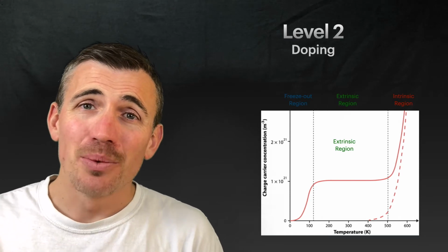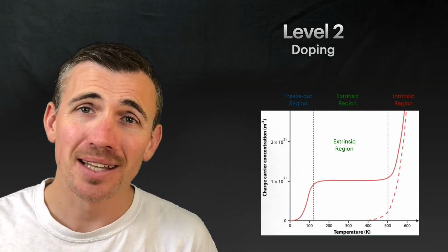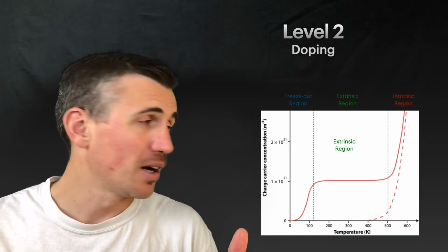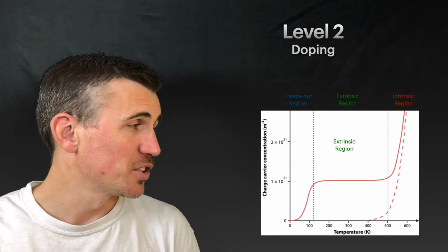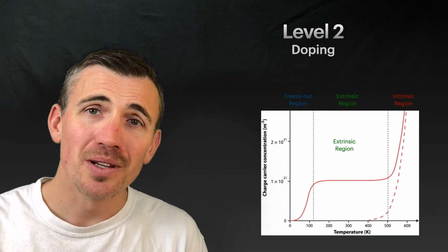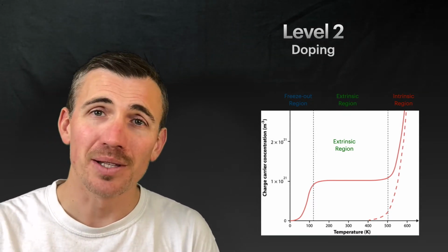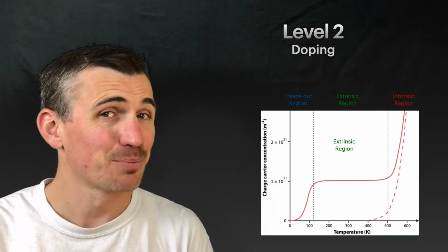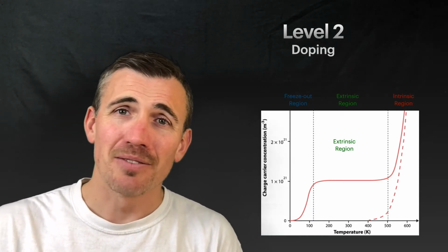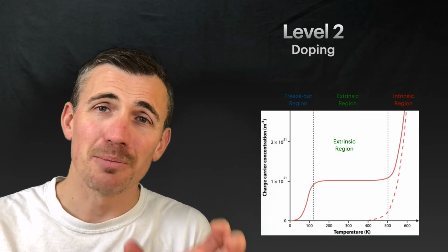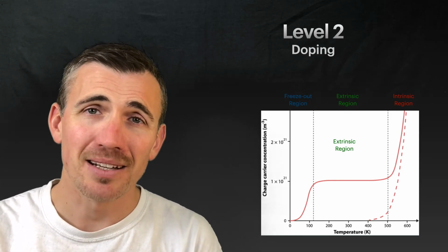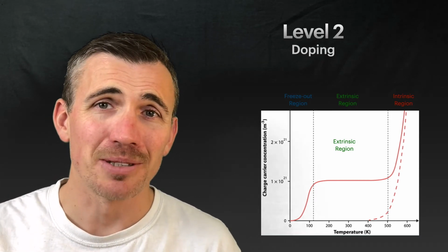Okay, so where are we? We have maybe not a technological revolution level of technology, but we have some cool stuff. With industrial processes, we can dope a certain amount of a certain density into a silicon lattice and arbitrarily tune how many charges we get per unit volume. We can tune our charge density. That's pretty awesome. That leads to some neat stuff. Still not enough though for a valley to be named after you. That will happen when we take a p-type and an n-type and shove them together. The interface of a p-type and an n-type semiconductor, that's where the magic really happens.